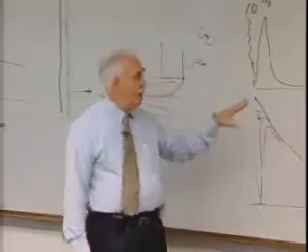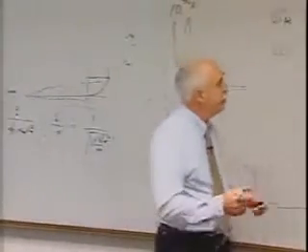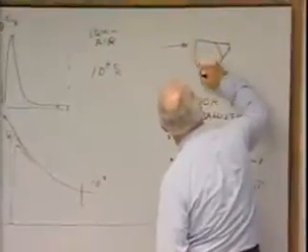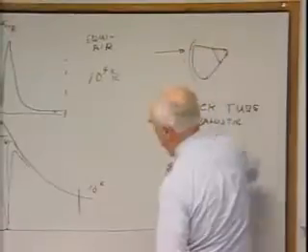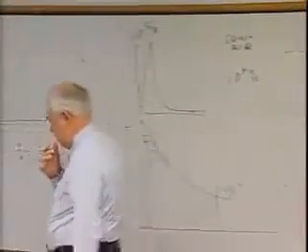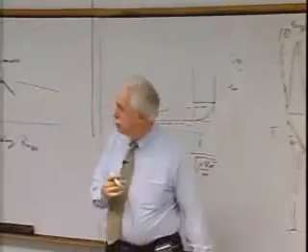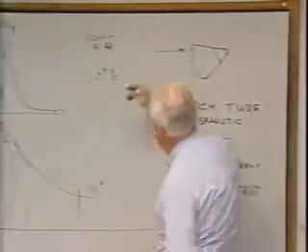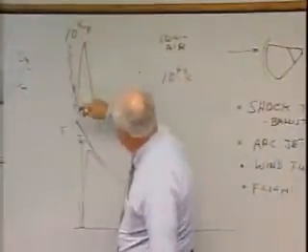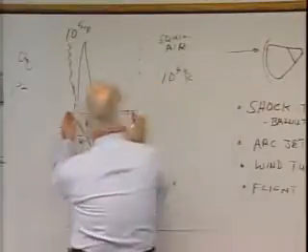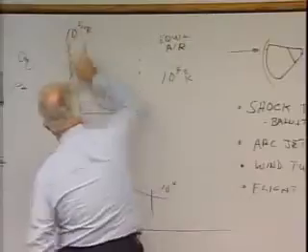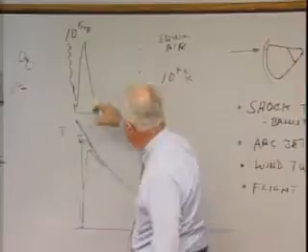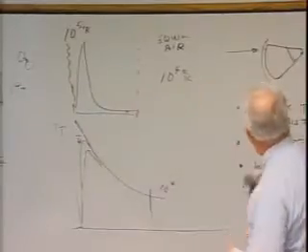Now, as I mentioned before, at peak heating conditions on Apollo, the shock, I can't draw it very accurately to scale, was on the order of about 10 centimeters or 4 inches there at peak heating. Is that the thickness of the shock or the standoff distance? The standoff distance, thank you. The shock is relatively thin, a few mean-free paths. Some people might call this effective shock thickness, but I term the transition to higher temperature the shock thickness, and then the relaxation, a relaxation distance.